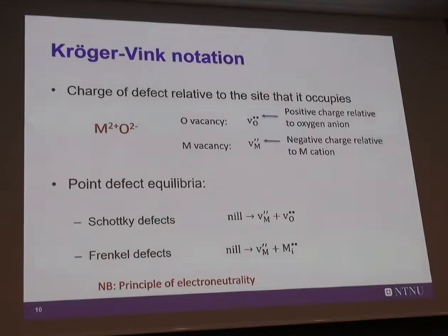If you look carefully here now, you see that both of these point defects don't create or annihilate any charge. So the principle of electroneutrality is very important when you talk about point defects. If you take the sum of the charges here, in both cases, the sum of the charge is zero. So one defect is counterbalanced by another defect. That's always the case, and very, very often neglected in the literature. Very important point, and I will come back to that in a moment.